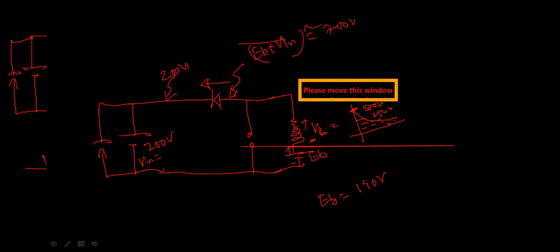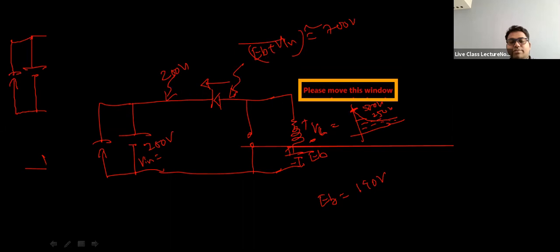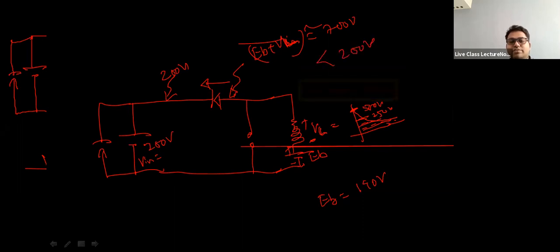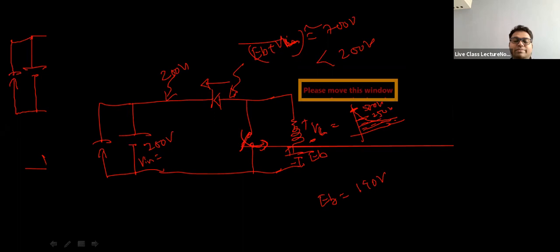Yes. Now, as the energy drains out, the value of E back will be almost decreasing, and that VL voltage will keep on decreasing, right? Before the whole voltage goes lesser than 200 volts, I'll switch this on again. I'll switch the switch on again, recharge, remagnetize the inductor, and I will again leave it. Then this cycle will be continuing, right?